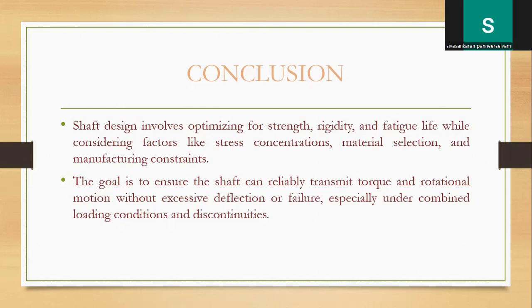Design factors like stress concentration due to bending and torque, material selection, and other manufacturing constraints are the most essential factors. The primary goal is to ensure that the shaft reliably transmits torque and rotational motion without any excessive bending or deflection under combined loading conditions.